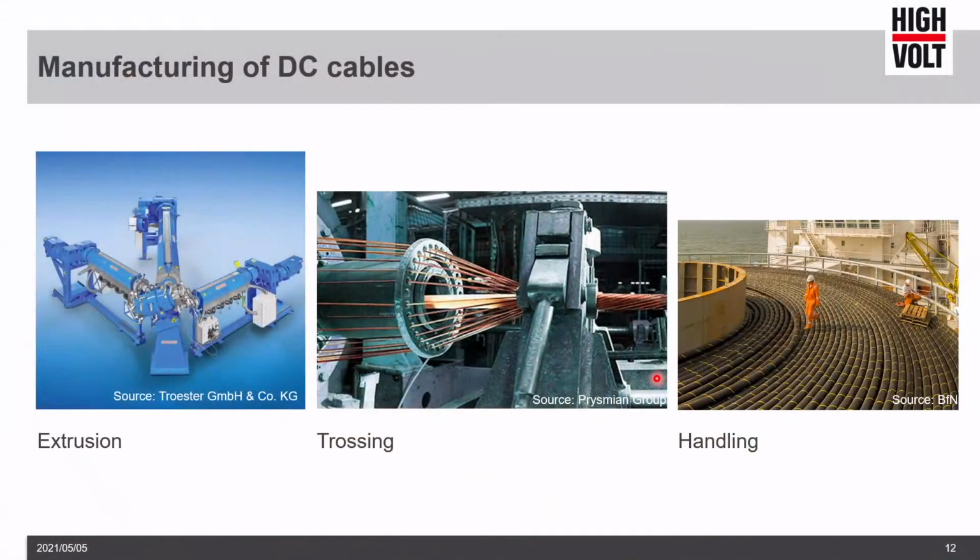Another thing which comes into existence, so to say, in the production of certain types of these materials, the XLPE versions, is that they need an extra production step, the degassing, meaning you put lots of heat and ventilation on the cable, and some volatile components, some gases, as you could say, are removed from the insulation, and it increases the performance of the insulation.